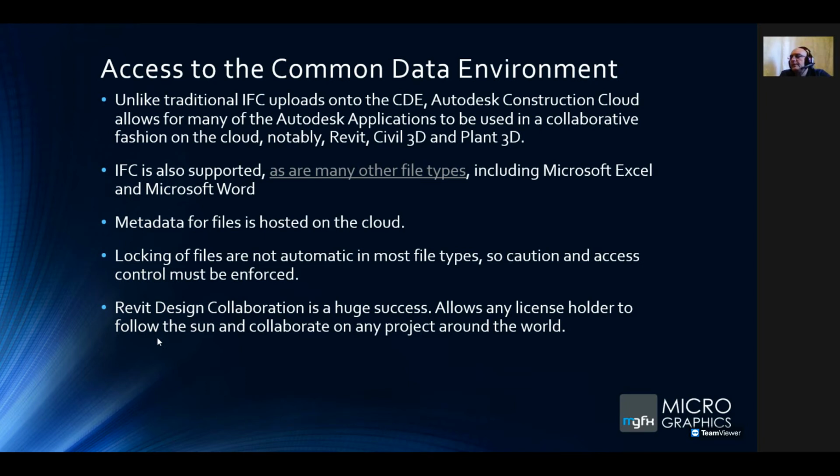What we do in Revit is we print to PDF, and as soon as you print to PDF, the cloud can extract the metadata from the printed files that you upload using optical character recognition. For sheets, markups, and creating design issues to assign to other people, it's very useful, and the metadata is extracted automatically. The metadata doesn't travel with the file if you download it, but it sits on the cloud. That's another reason why you need access to the cloud, so you can immediately also see the metadata for that file that is up there.